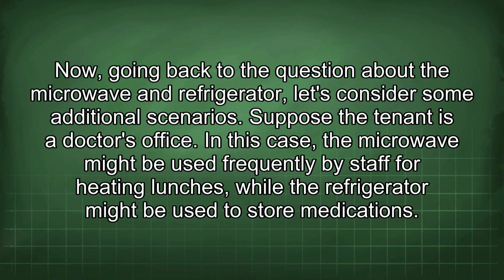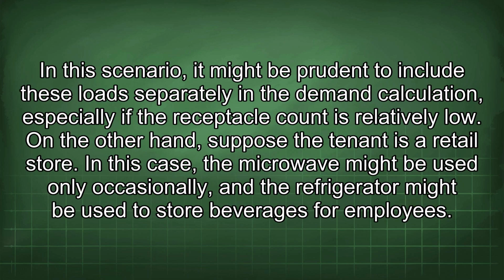Suppose the tenant is a doctor's office. In this case, the microwave might be used frequently by staff for heating lunches, while the refrigerator might be used to store medications. In this scenario, it might be prudent to include these loads separately in the demand calculation, especially if the receptacle count is relatively low.